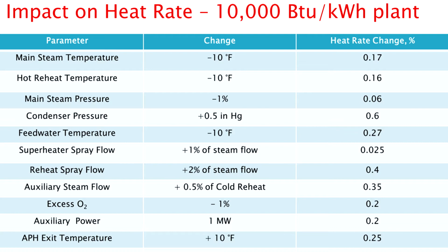Again, why is oxygen, why is air so important? Remember, fuel needs air to burn. Fuel needs oxygen to burn. So for every pound of pulverized coal that you inject, you need theoretically about 8 pounds of air. So there are a lot of losses that happen with that air after it does its job and burns the fuel. As it goes out the stack, you lose some energy out of it, and I'll show you the numbers on that.